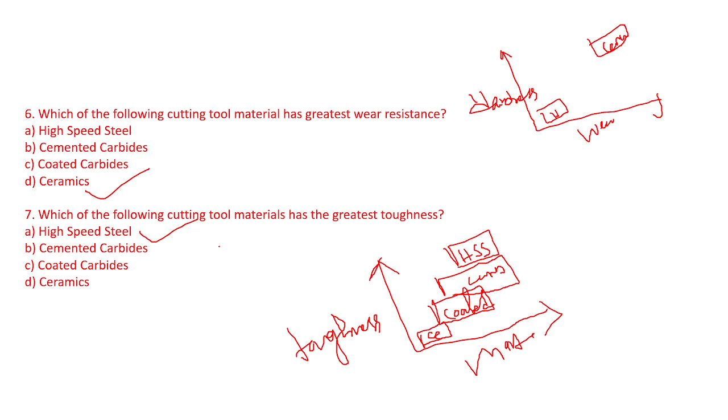So on the usability of ceramic cutting tools, they are used at the highest cutting speeds recommended, with square or round inserts with large nose radius, on rigid workpieces and rigid machines. Negative rake angles also, as we have studied in metal cutting, mean less force is applied directly to the tip of the ceramic cutting tool. Those are the basic parts of the tools.